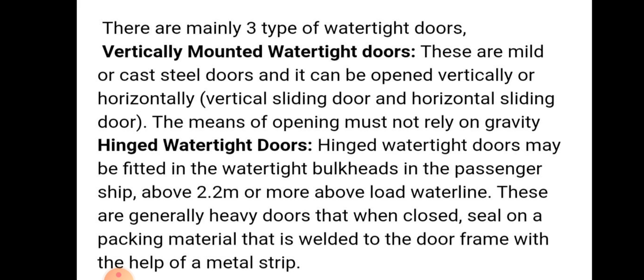And hinged watertight door. Hinged watertight doors may be fitted in a watertight bulkhead in a passenger ship above 2.2 meters or above the load water line. These are generally heavy doors that, when closed, seal on packing material that is welded to the door frame with the help of a metal strip.